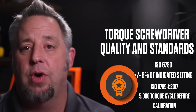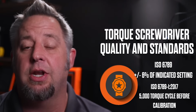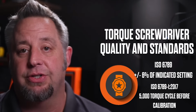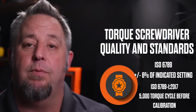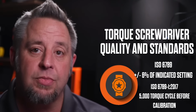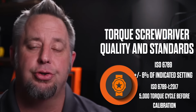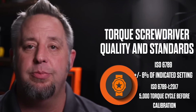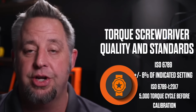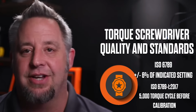In that standard as well, the tool must remain within its calibration range for at least 5,000 cycles. Those requirements deal with torque screwdrivers only. There is some change when we look at torque wrenches, and we'll note those at that time as well.